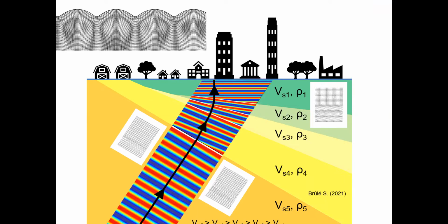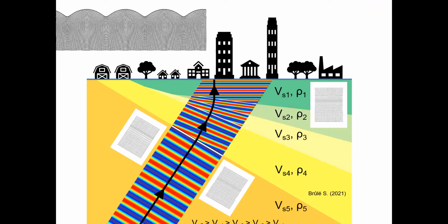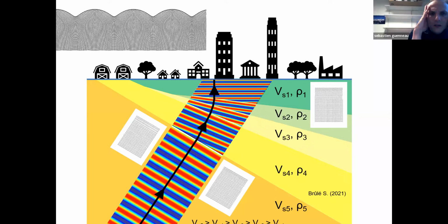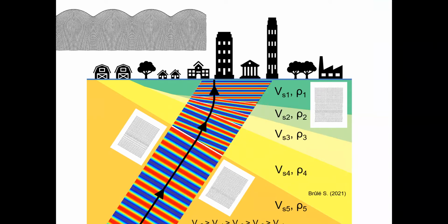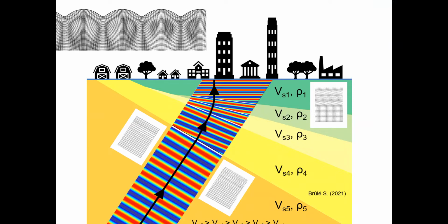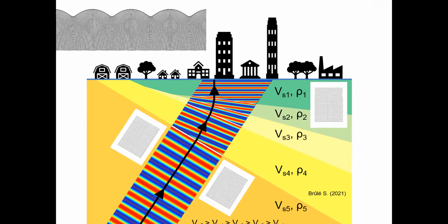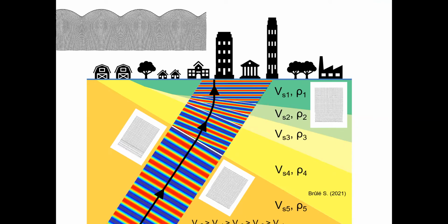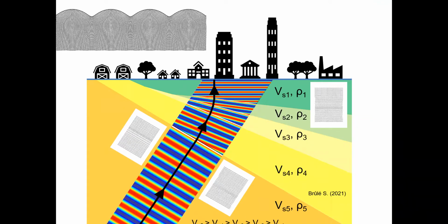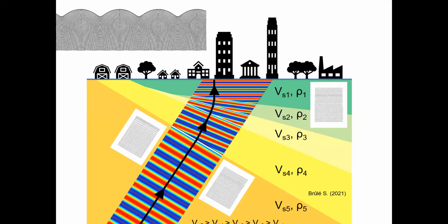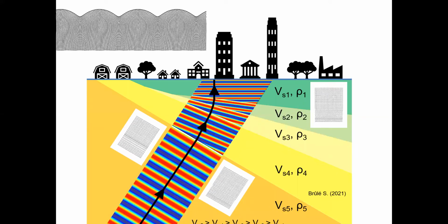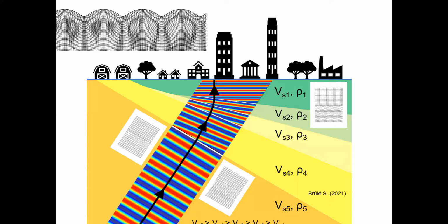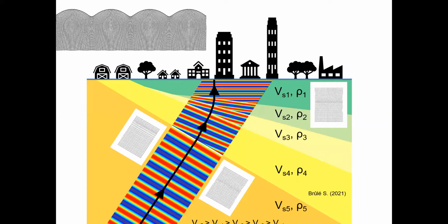It can be efficient for the wind, or sometimes for the earthquake. It is 5% of the mass of the building. The tuned mass damper is very interesting for the comfort of people inside, because we are limiting the displacement.